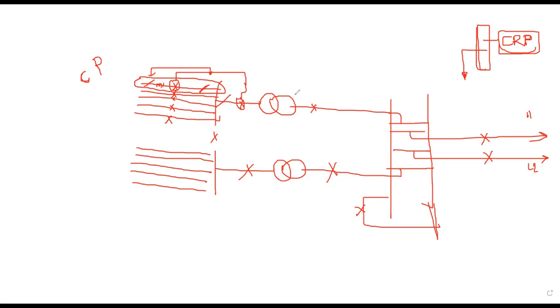Let's assume my protections are general protections. It depends upon the type of protection you have adopted. If the unit protection on the line cannot be accommodated in one panel, then we have 2 panels for each line. That will come in our next discussions. For the present, let's assume that each feeder, each breaker has 1 panel.